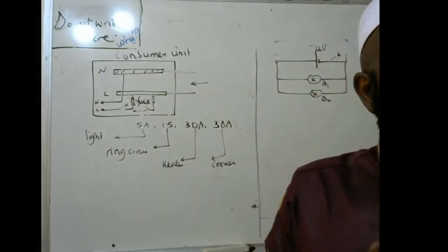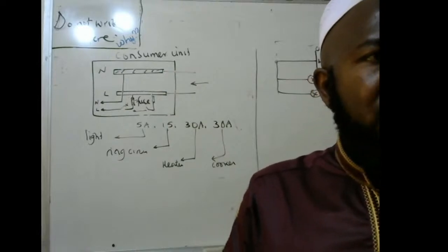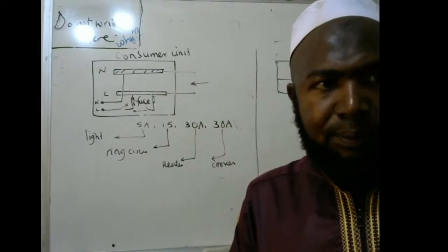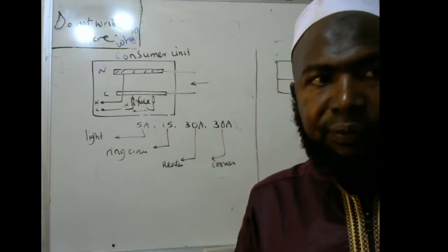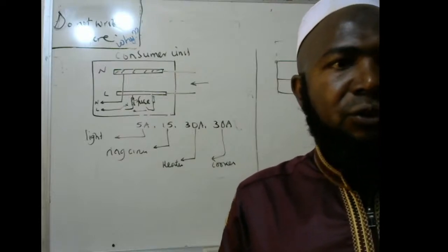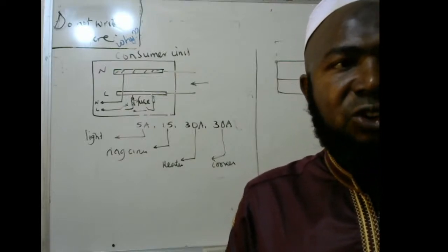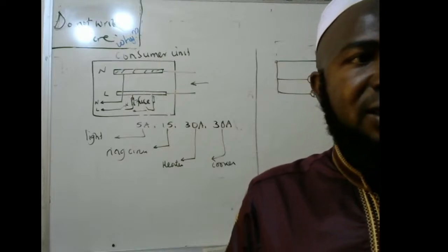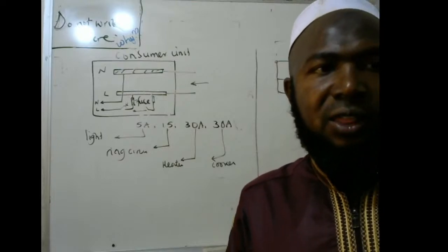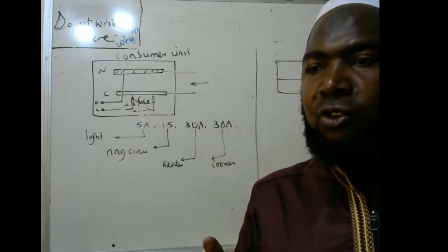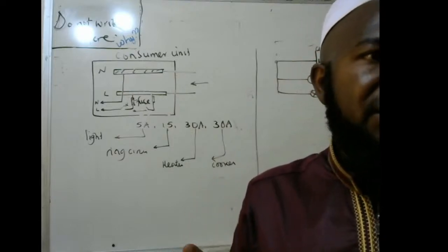So that's why we are saying the supply, electricity enters the house through the supply cable from the power. The supply cable consists of two insulated wires, the live wire and the neutral wire. The neutral wire is earthed at the local substation and therefore at zero potential, so the neutral wire does not cause electric shock.